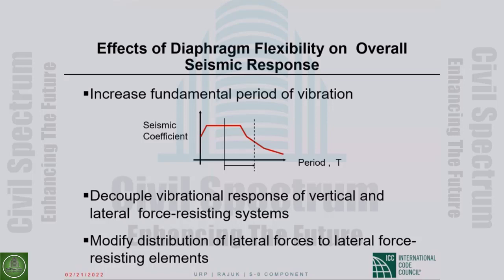When the diaphragms are very flexible, they would increase the fundamental period of vibration of the building. Remember, we calculate the period of vibration as height raised to the power something, considering only the vertical elements of the seismic force resisting shear walls. If it is a frame building, it is a coefficient times height raised to the power something. If it is a shear wall building, it is another coefficient times height raised to the power something else.